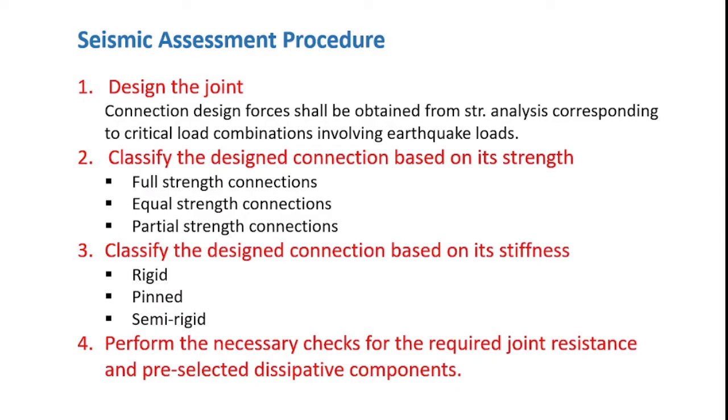So basically the seismic assessment procedure consists of various steps. Before stepping into Idea Statica for the seismic assessment, we need to complete some homework, which is described here. The first such procedure is the design of the joint. So we have carried out a structural analysis of the given structure, and corresponding to the given joint, we can obtain all the design forces corresponding to the critical load combinations involving the earthquake loads. Now, using these earthquake loads, we need to design the joint.